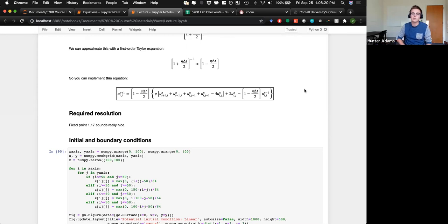And if you're trying to build the biggest drum that you can possibly build, you want to fill as many of the cycles as you can between the 48 kilohertz audio samples with calculation. You want to be updating as many nodes as you can in that time before the next audio sample comes in. So what that means is you want to build some sort of state machine that combines serial processing with parallel processing, right? So you don't want to just parallelize individual nodes, because if you're only parallelizing individual nodes, you're going to spend most of the FPGA's time doing nothing.